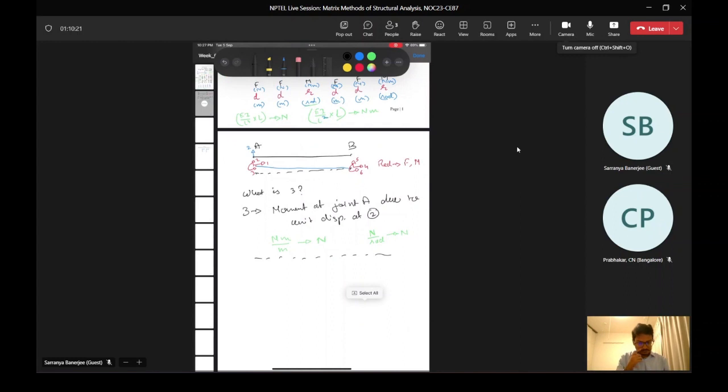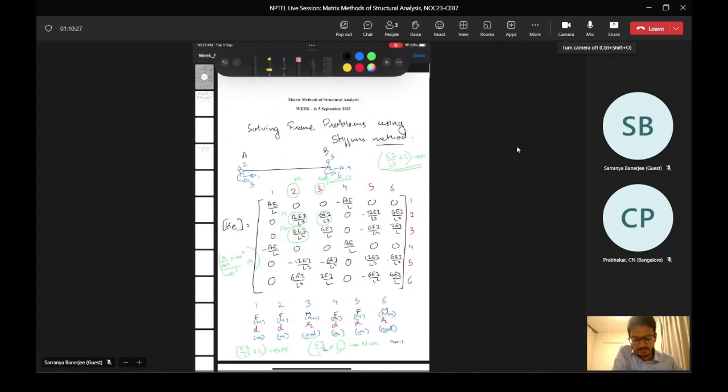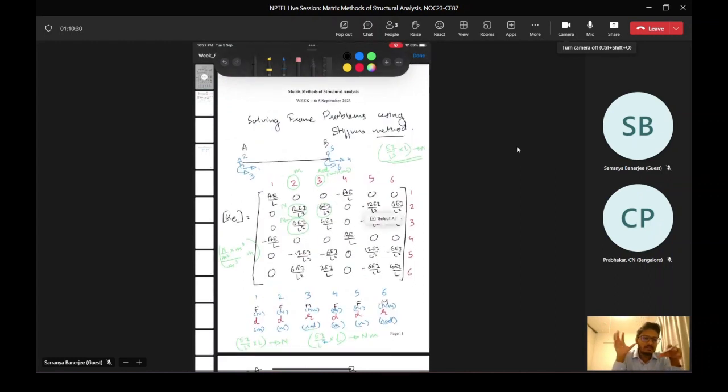Now what we basically did in the element stiffness matrix of the frame element is we merged two elements, one truss element and one beam element, and put them together. But if we remember, when we did the problem for the truss element, we had some transformation because the trusses were at different angles. For the beam element, we did not, because the beam was always in the horizontal plane, always having the same angle. There is no beam going like this, like a triangle. So what will happen if a beam goes like a triangle, like this?